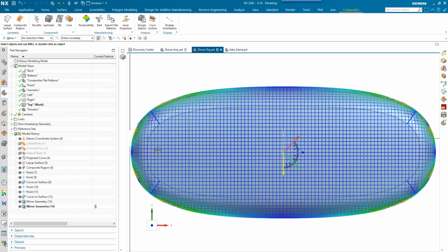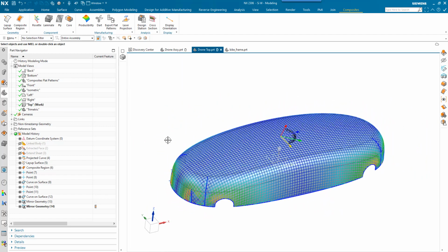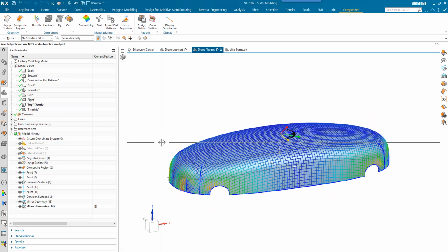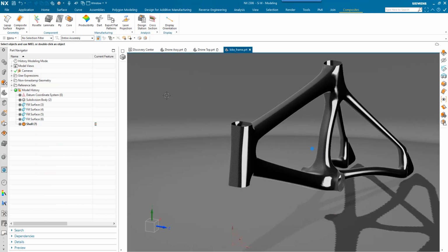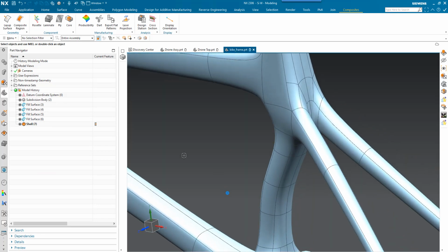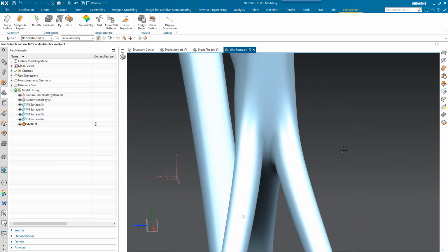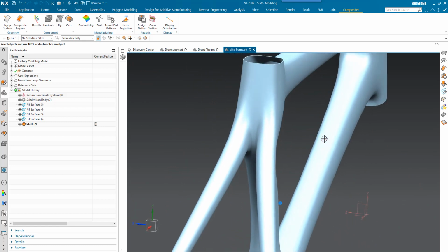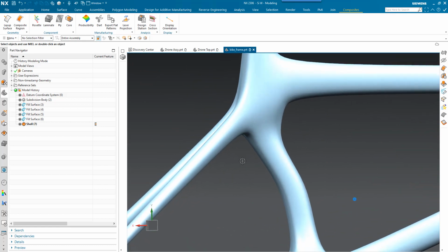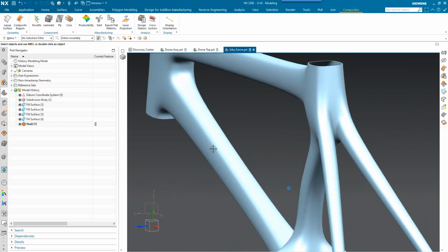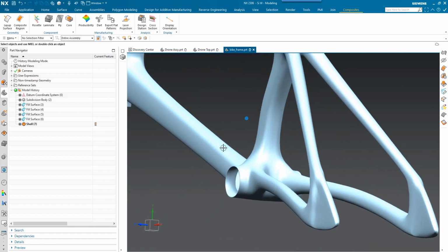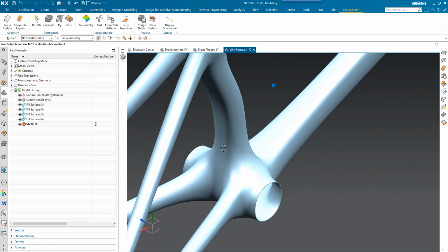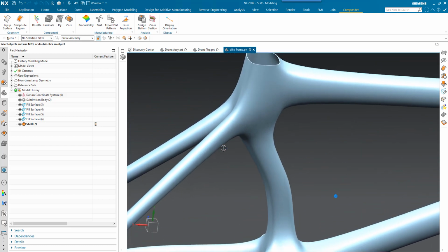So that's all well and easy on something like this, which is very simple in shape, or even on your bigger parts of a mountain bike frame or any bike frame that have got very gradual changes in topology. But where you get into areas where you've got really complex topology or really tight corners, you can imagine that trying to cut out really complicated flat pattern shapes gets quite challenging, and no wonder you get inconsistencies in wall thickness when you're building shapes like this that have got really complex structures, especially mass producing them as well.